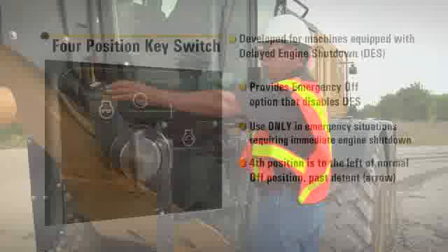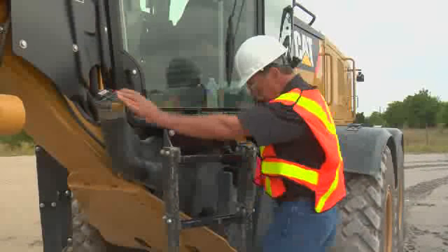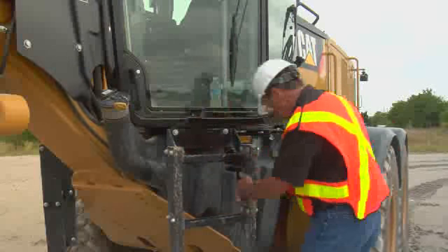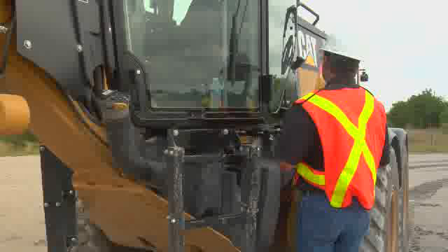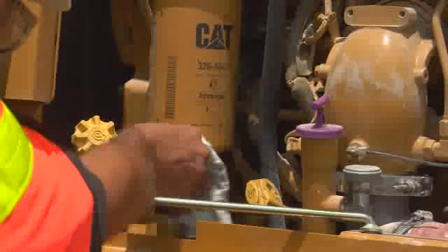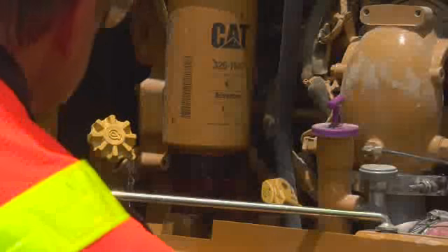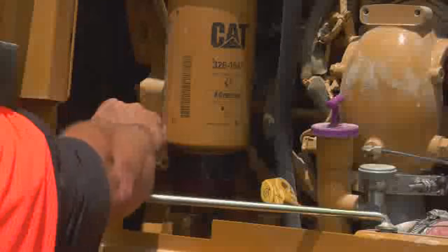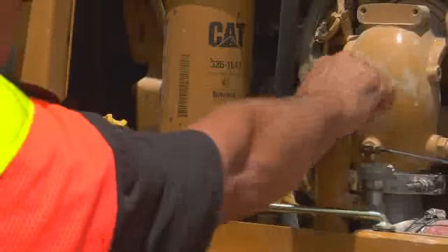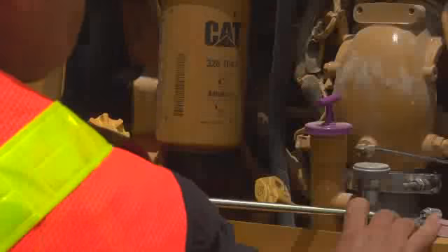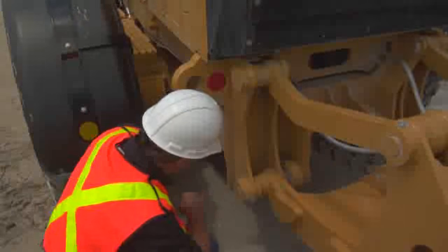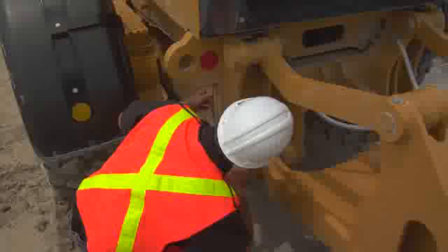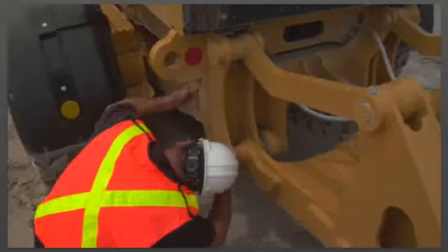On Tier 4 motor graders and articulated trucks, an electric fan with the delayed shutdown feature is used to reduce heat in the engine compartment instead of delayed engine shutdown. These machines continue to use a 3-position switch. When leaving a motor grader or articulated truck, the battery disconnect switch should not be turned off until the fan has run its cool-down cycle.